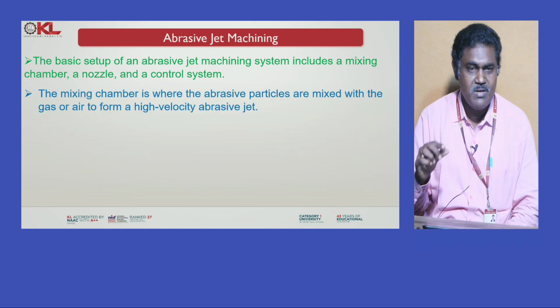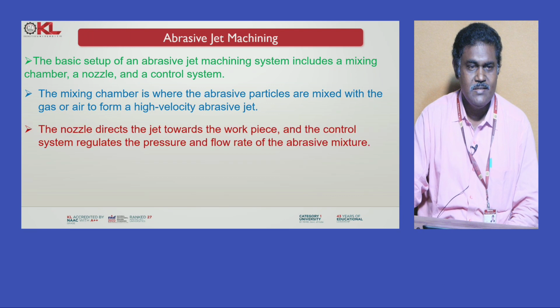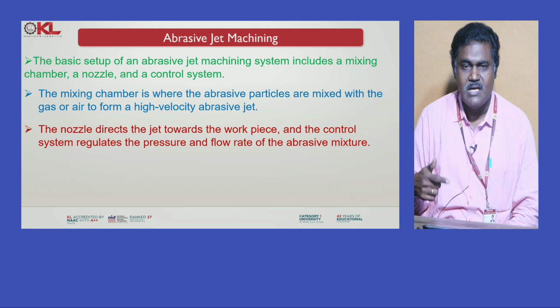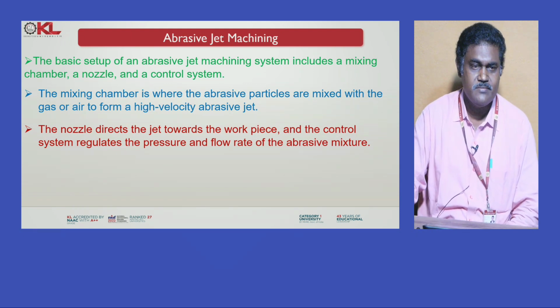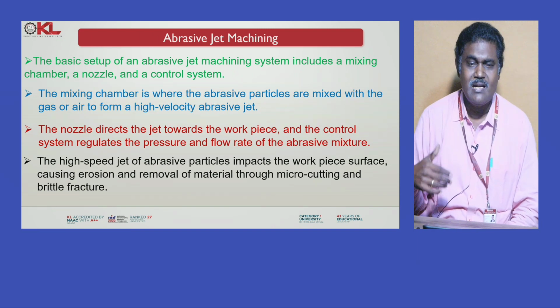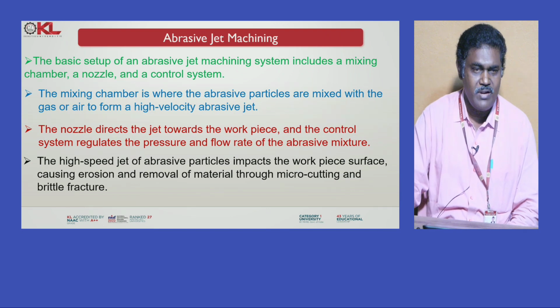The mixing chamber is where the abrasive particles are mixed with the gas or air to form a high velocity abrasive jet. The nozzle directs the jet towards the workpiece and the control system regulates the pressure and flow rate of the abrasive mixture. The high speed jet of abrasive particles impacts the workpiece surface, causing erosion and removal of material through micro cutting and brittle fracture.